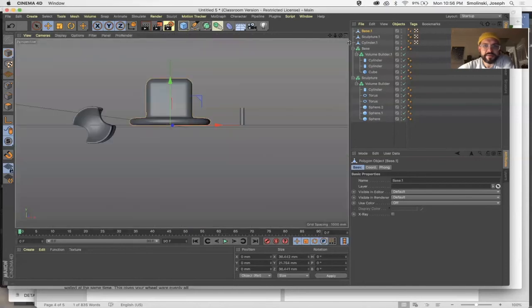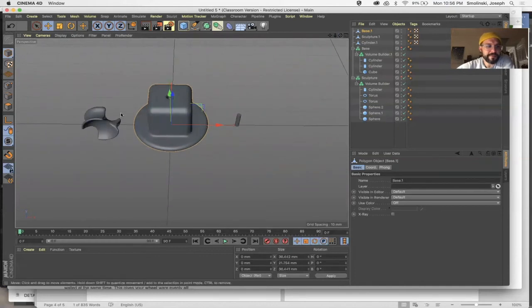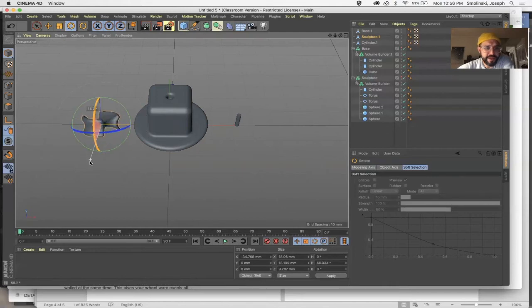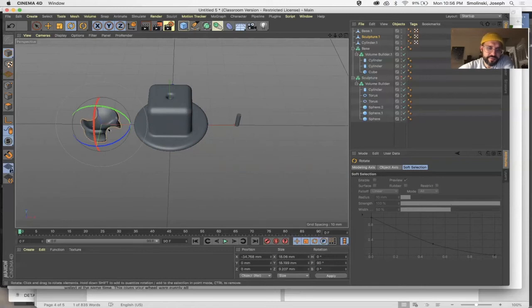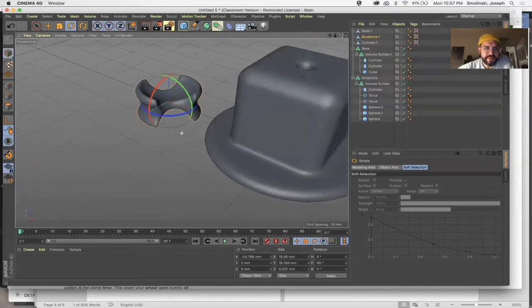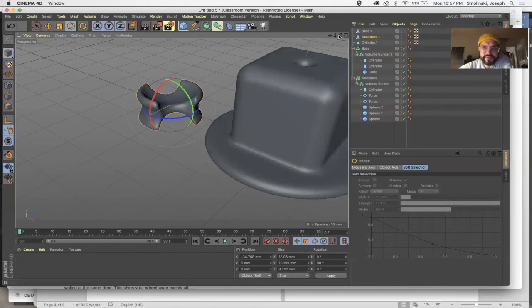Okay, let's go back to this and just think about how this is going to 3D print. Okay, so this thing is not going to print very well in this orientation. What I'm actually going to do with this is I'm going to rotate it. Let's just rotate it down like that. We're going to rotate it basically 90 degrees. And in this orientation, it's going to print much better. May need a little bit of scaffolding, but that's not too big of a deal. Scaffolding or the bridging that it creates to kind of print underneath objects or in the voids. It may or may not need any underneath here, but I think in this orientation is probably the best to